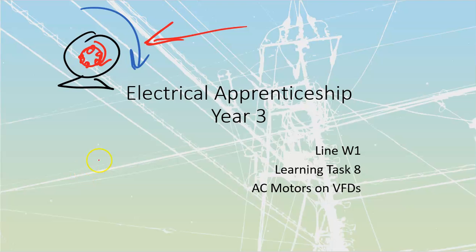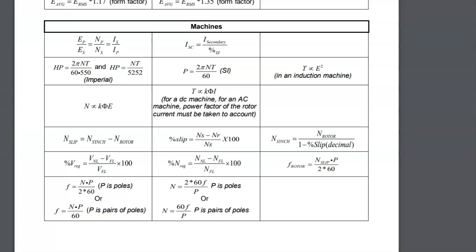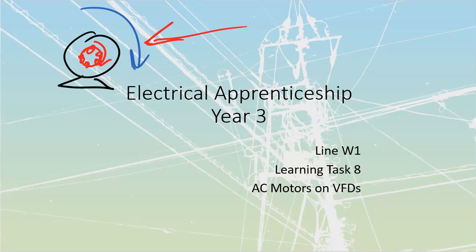We've got a formula for this. If you go back to your ITA formula chart, you should recognize it right here on the bottom. Over here, we see that we have N, which is my speed. N is equal to 60 times my frequency divided by my pairs of poles. That's going to determine what my value of speed is going to be. Taking that back onto this one over here, 60F over P, let's write that one down.